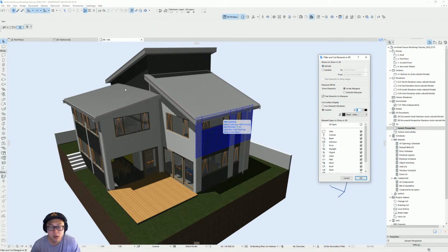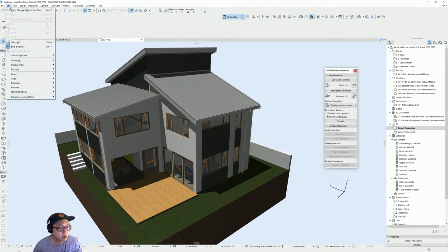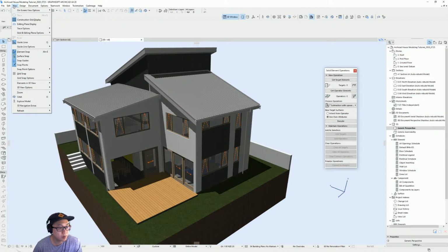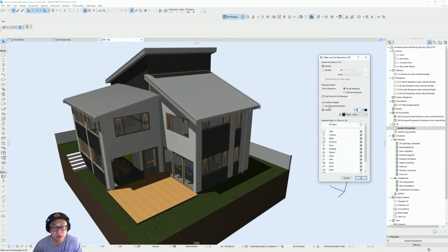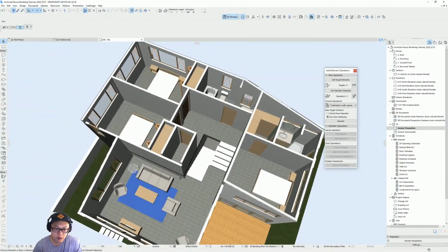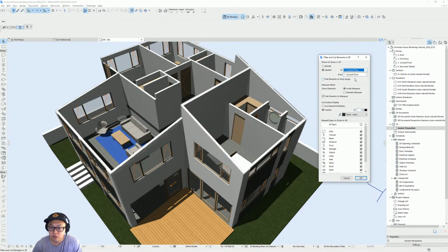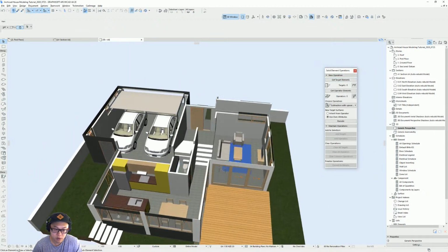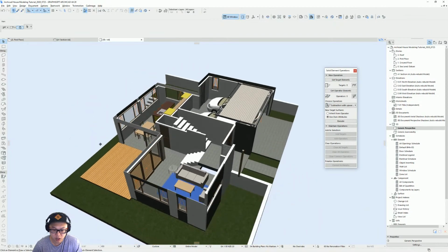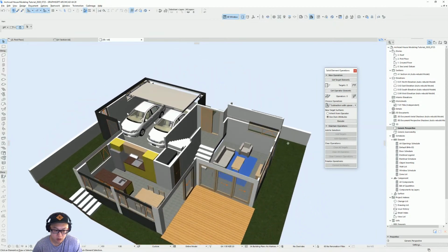This will pop up. So you go to View, Element 3D, Filter, Cut Element, and limited ground floor to first floor. I will show you that. And if you want ground floor, it's going to be like this. Good way to visualize it.